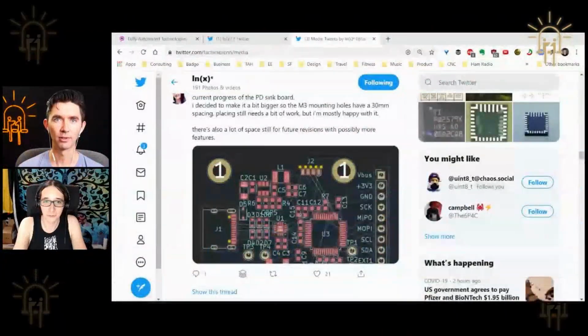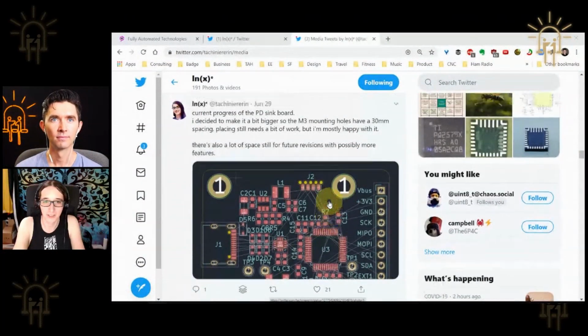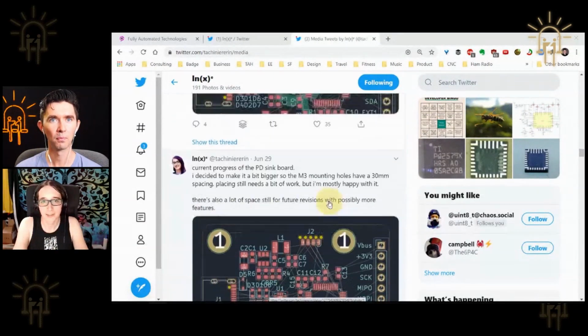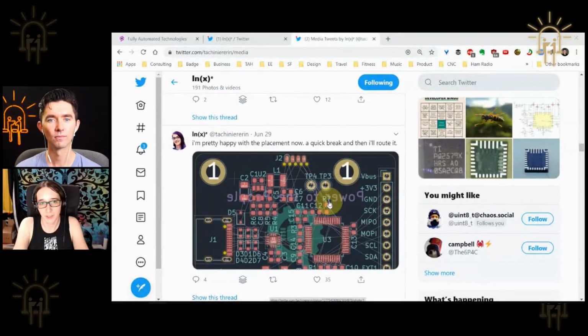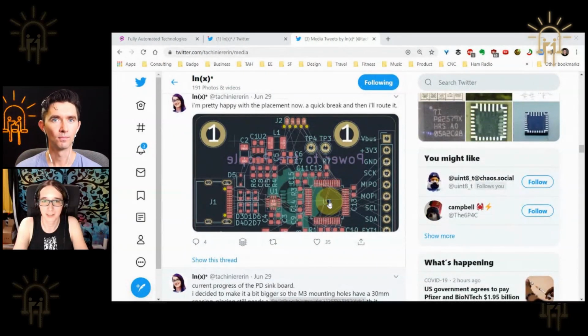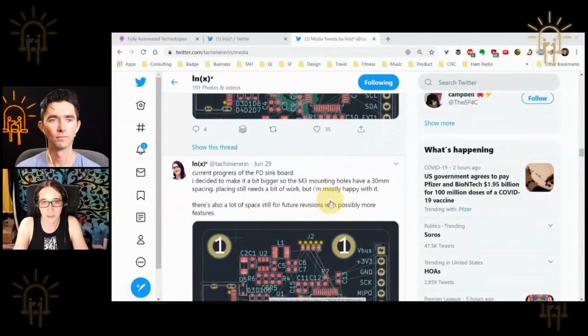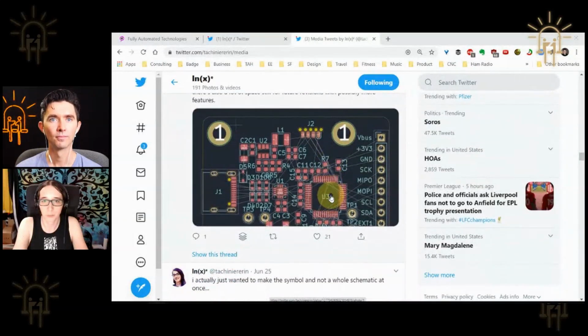When I take a look at it, if it takes me too long to understand what's happening here, there's one of two cases: either I don't understand it well enough yet, or I need to redo the layout because it's too complex. Even with really complex stuff, you can still do a simple layout. And subcircuits in KiCad are so amazing, splitting the layout up in functional parts. That's a really important thing, to help understand how things fit together.